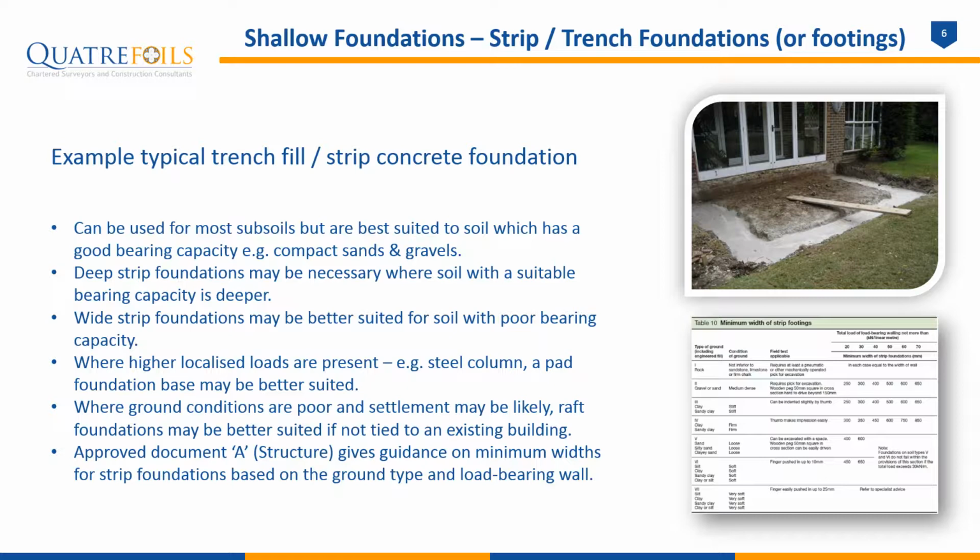So strip or trench foundations can be used in most soil types, but are generally best suited to compact sands and gravels with a good bearing capacity. In some instances where the good soil is deep in the ground, say over a couple of metres down below a weaker top surface, this option might not be the best choice for foundation, both in terms of cost and physical practicality to dig a deep trench. An alternative here might be the use of micro piles, for example.